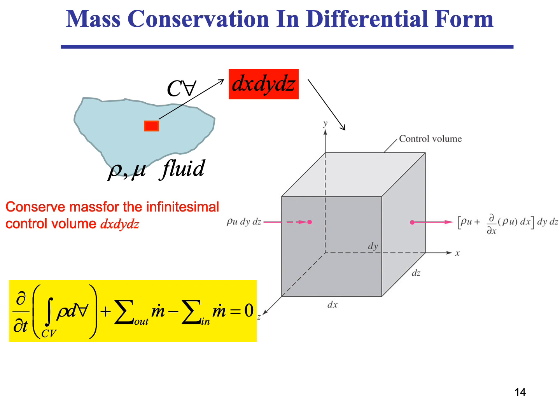We have our box, our control volume, little tiny dx, dy, dz fixed in space, and the flow is going through it and leaving from it, from all 6 faces and into and out of the page. And the velocity as it comes in and as it leaves varies by a small amount, delta v and delta u and delta w. And those, as we have seen in the previous slide, we can relate to the slope of the velocity and the value of the velocity at one point.